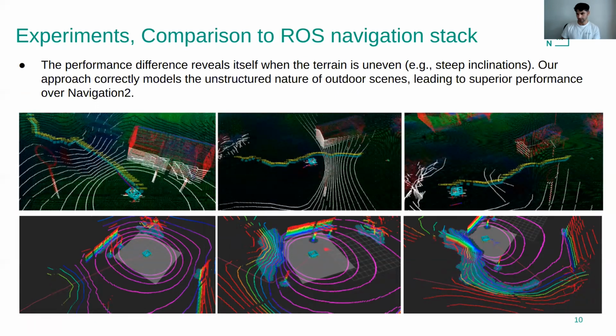And once it gets close, because there is a hill here, it starts to perceive this hill as an obstacle, but in fact it is not. So the robot changes its course according to a new plan. But even with that, the robot gets close to here, and again the traversable areas appear to the robot as obstacles. So eventually the robot gets confused and navigation fails.